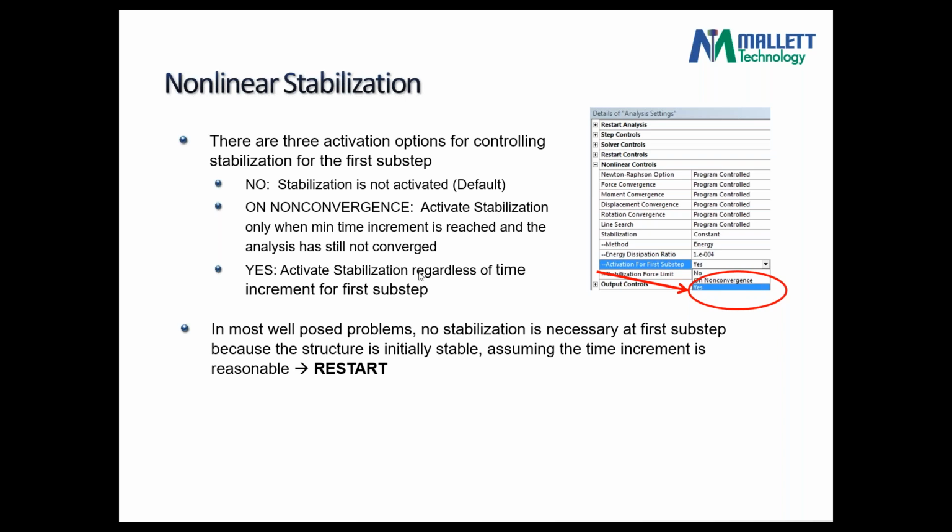In most well-posed problems that you define very nicely, no stabilization is used at the beginning. You really don't want it because you don't know how much of it to apply anyway, unless you know the structure and you're really doing some serious analysis and everything is in control. I found that most of the time you'll be doing some solution followed by a restart. So assume you solve a problem and you notice instability somewhere halfway, maybe at 20% of the load, 30% of the load, and you must save the restart files for every point. Then you want to go back and do a restart, activating the stabilize command and see how the solution goes.